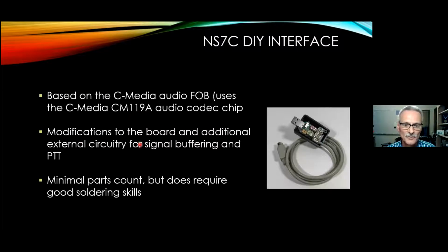We have to do some modifications to the board and add some external circuitry. We've got to put that push-to-talk connectivity in there, and probably some attenuation for the audio signals going into and out of the device. Really not very many parts are involved in what I did, but it will require some pretty good soldering skills, and you'll see why as I go through the next couple of slides.